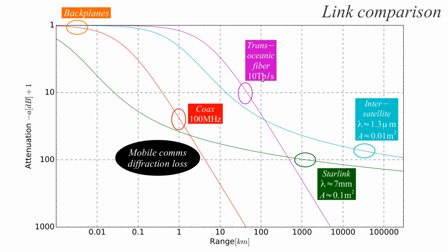So transoceanic optical fiber may have a repeater installed in an underwater repeater every 50 kilometers at 10 dB attenuation. And in this way we reach the other end of the ocean. Of course, across the ocean we need to cross 5,000 kilometers. We need on this line around 100 amplifying stations for the optical fiber, where we span 50 kilometers with each span of this link.